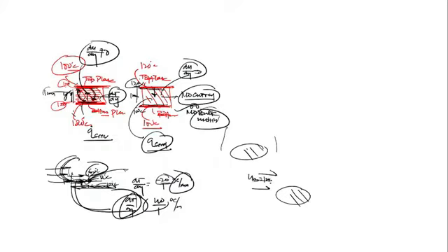Obviously in this case, why? Then what should the answer be? The answer should be, sir, in this case the heat transfer, here also convection is there, and here also convection is there. Listen, here also there is heat transfer through convection. Why convection here? Because any fluid layer on the surface of the solid will be at high temperature, and any fluid layer away from the surface is at low temperature. That causes a density difference, and that density difference causes the buoyancy effect, and due to the buoyancy effect there is a convection current. Here there is free convection, but there is also forced convection. Is this clear?